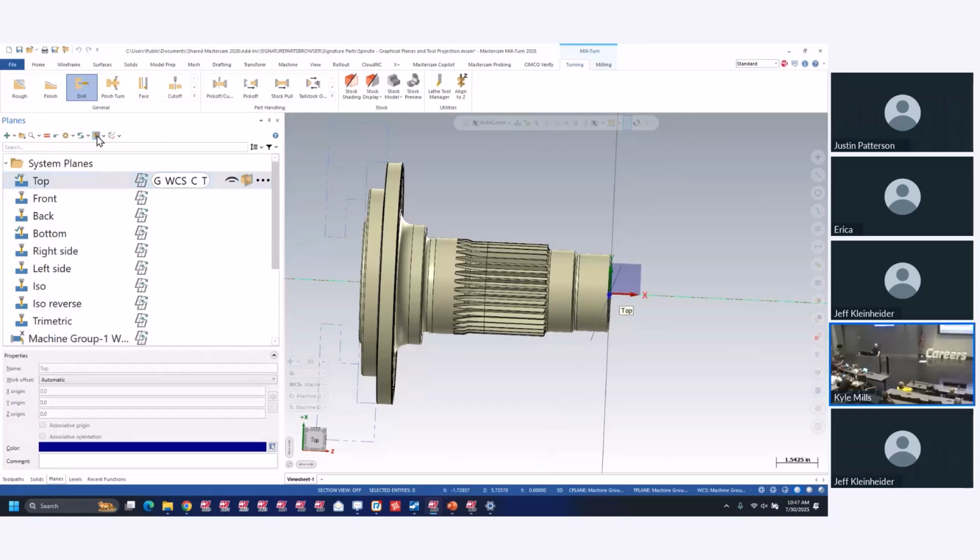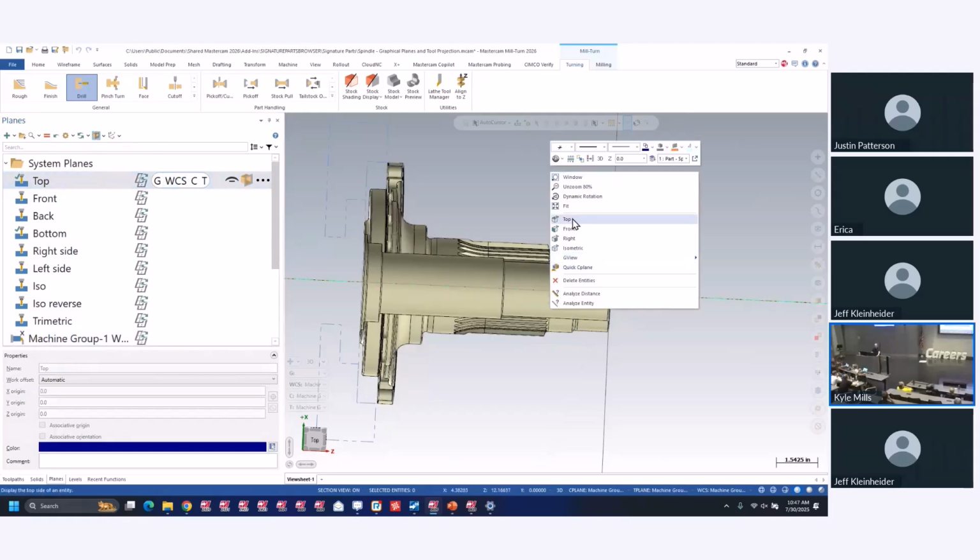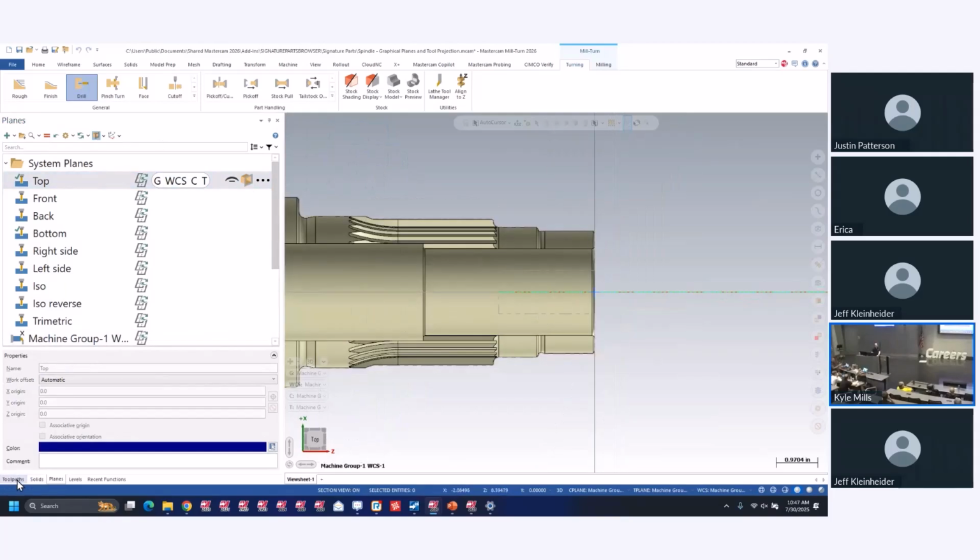While he's doing that, I will say where I think you're going to see the win in this is subspindle work. How many times does that confuse everybody? Working negative versus 100% positive subspindle. Subspindle work confuses even me, even though I've done it a million times. You've got to switch from going to a negative value to a positive value. And it's like, wait, no, but I want to drill into the material. Okay, but that's technically positive on this machine.